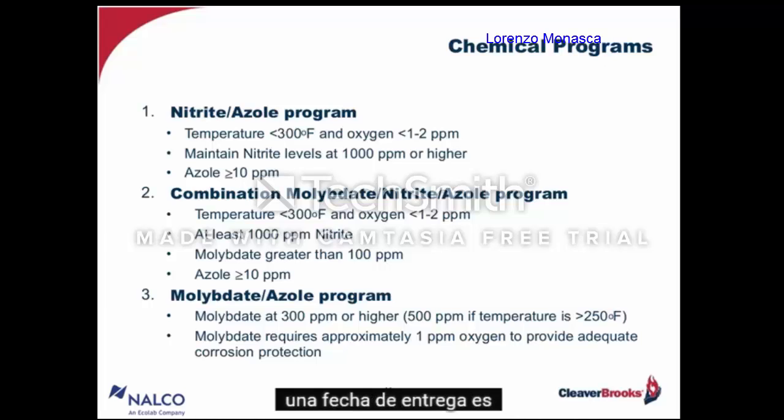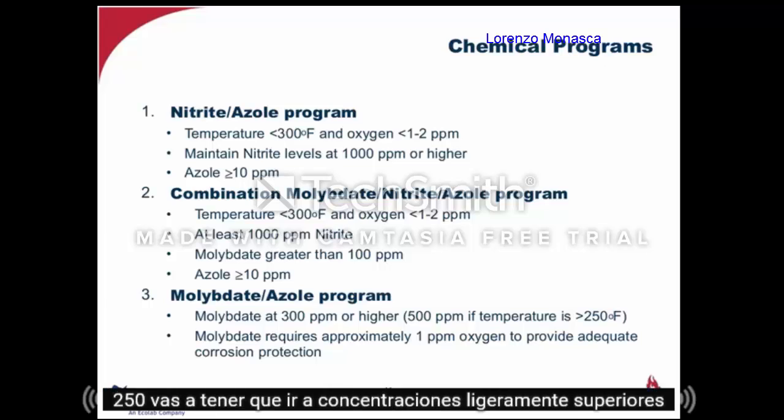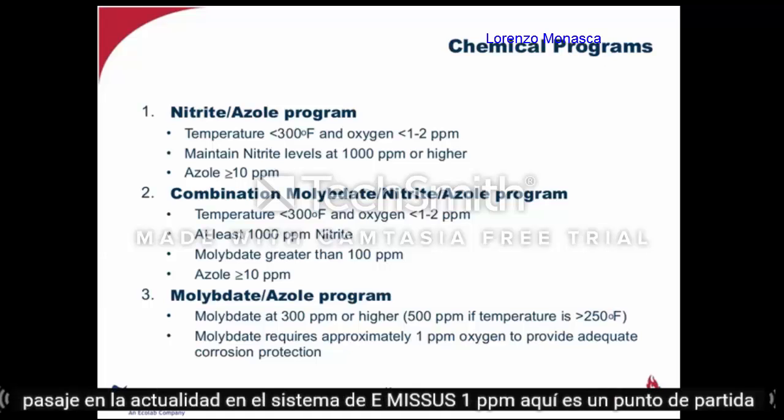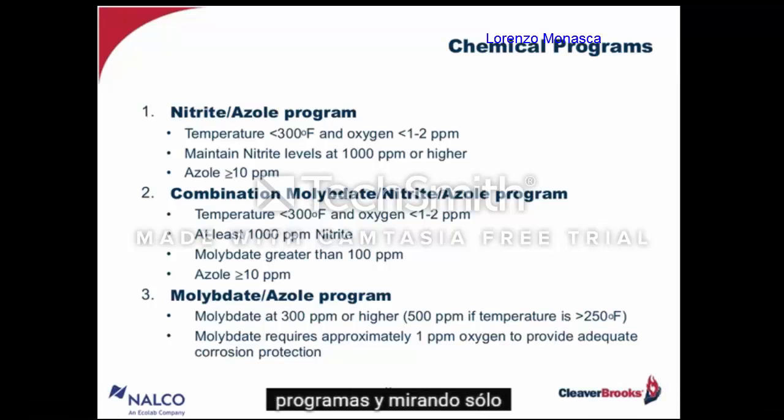The molybdate is there at 300 ppm. If you're above a temperature of 250, you're going to have to go to slightly higher concentrations. And molybdate actually requires a little bit of oxygen present in the system. I've listed 1 ppm here as a starting point.